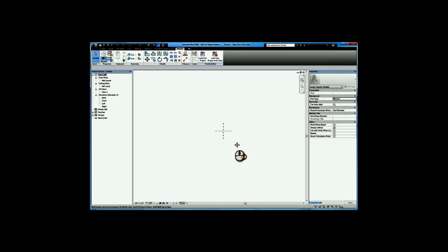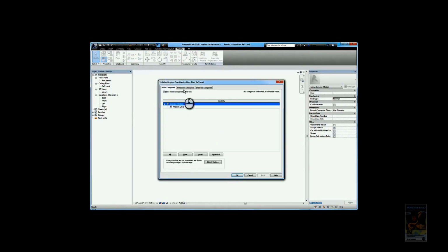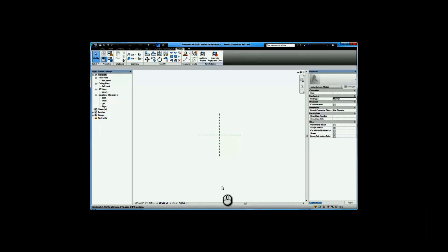If I try to zoom out, you're not going to see elevation marker designations. A lot of people are used to seeing left, right, top, and bottom elevation markers. They're already created. Those elevations are created for you. If I open up the Visibility Graphics dialog box and go to Annotations, if I take a look, you will not see the elevation marker annotation category to display that data. So the way to look at it is front, left, right, or back. Front is standing here looking this way, back is here looking this way, and left and right.